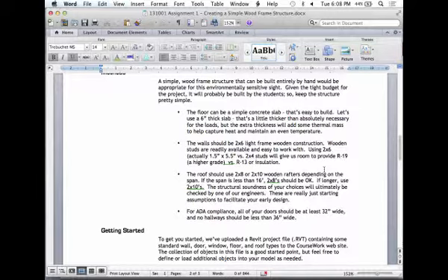Stone you actually see too. Often we'll do stone kind of at the lower part of the wall. So there might be some stone layered on here, kind of stacked up. A very common material on campus, almost all the buildings, is stucco. Stucco is really just cement plaster. We call it stucco when we put it on a wall. It'll be about 1 inch of cement on the outside here. Very durable, well, relatively durable. It still cracks, but it's good for thermal things too. It absorbs a lot of heat during the day, re-radiates it throughout the day, so it gives a little bit of thermal mass.